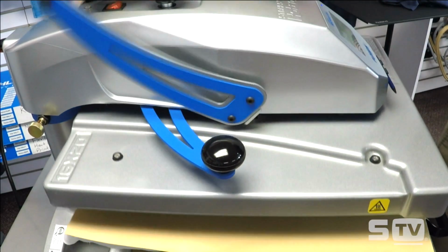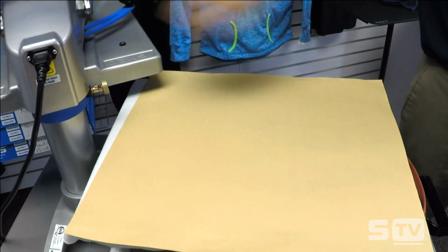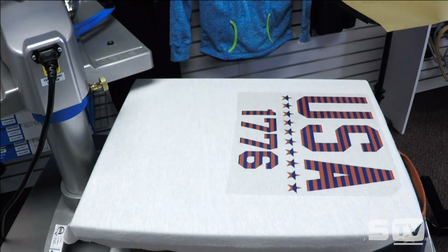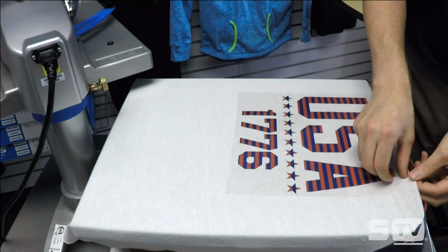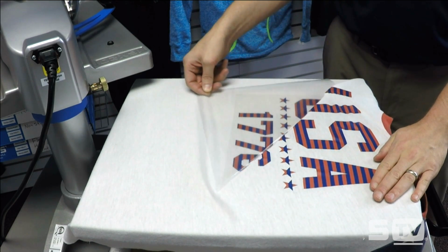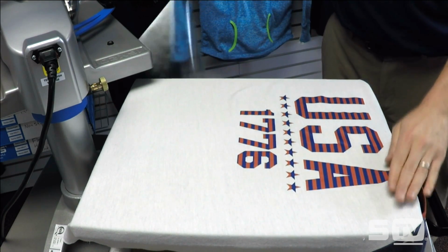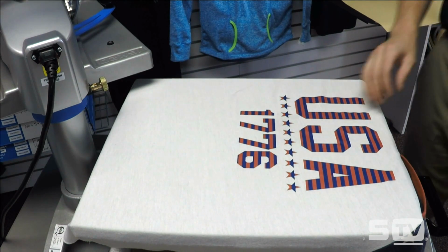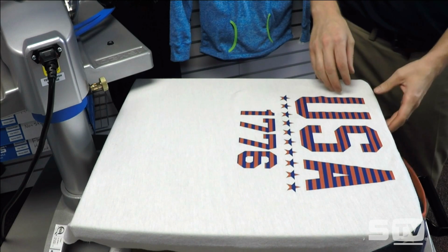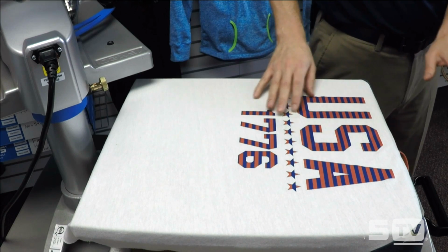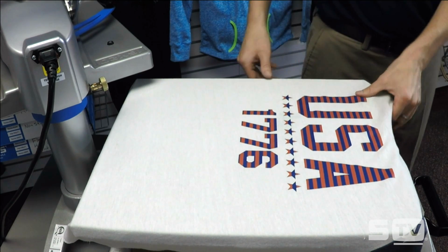Absolutely. Will the pattern fade or mess up if pressed on a higher temp, like 320, to apply with glitter flake? Okay, so good question. As I'm peeling this back, warm peel, will the pattern fade if pressed at a higher temp? No. I mean, 20, 30 degrees variance isn't really going to harm this product. You just want to make sure that you get the complete recommended temperature for the time. And we're going to do a mixed media here with glitter flake in just a bit as one of our profit-making ways, but 320 degrees is no problem for this. You won't experience any negative results at that.